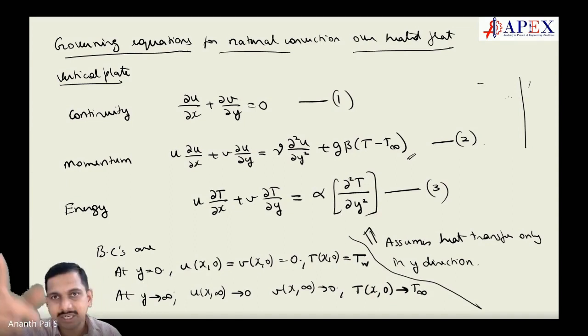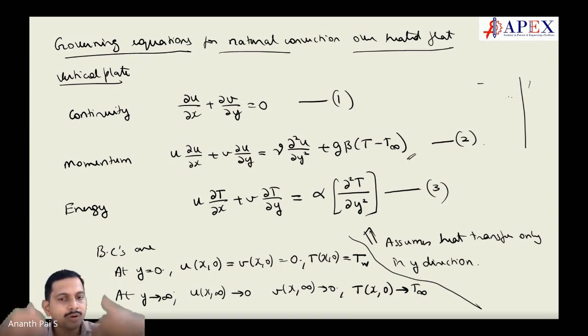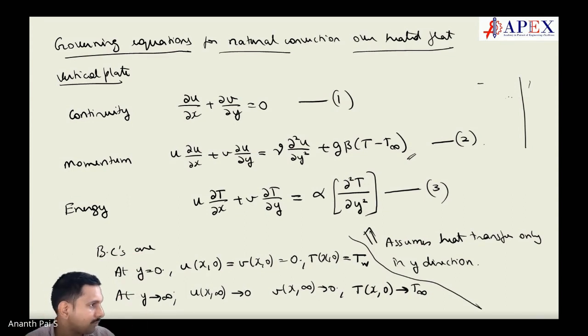That's how, if you see Malalasekera, we have a book on CFD by Malalasekera. You can see that. First, he starts with the diffusion equation with all the central differencing. Once that is done, next convection diffusion. Then next, without acceleration, only the diffusion equation. Next, the acceleration diffusion equation. After that is done, then the pressure velocity coupling. Pressure velocity coupling is the most difficult one.